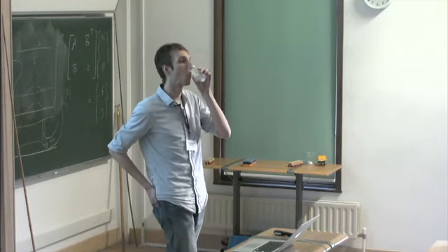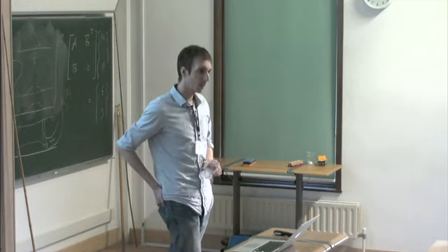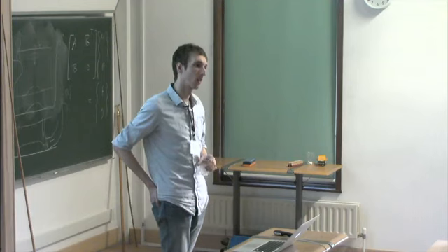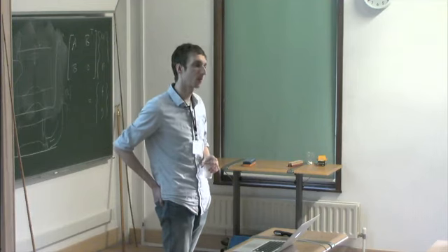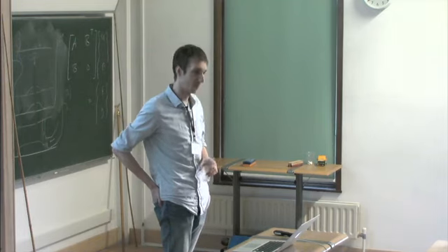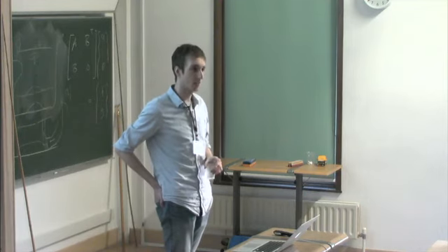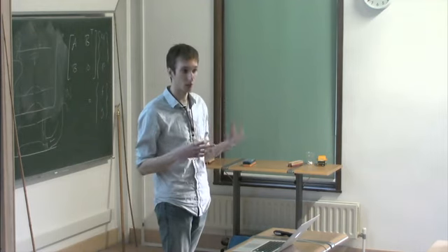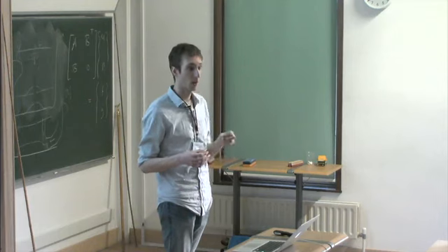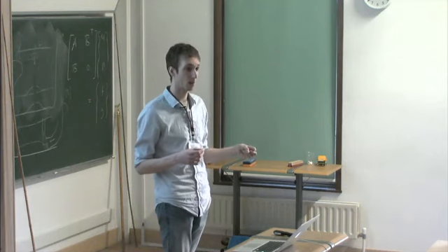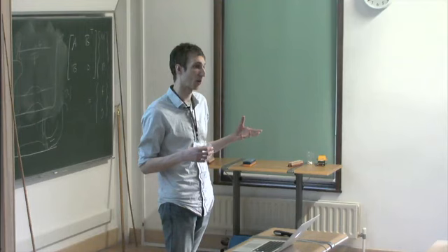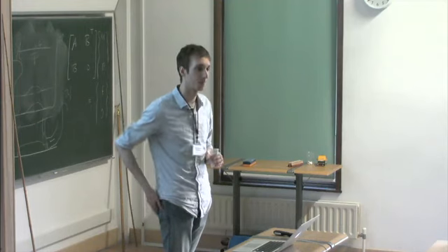As you said, when it is swelling halfway, it's not spherical anymore. Did you do the experiment, or if not, what do you think will happen? You take it out before it has reached final. Would it redistribute, become spherical outside water? So that's a great question, and yeah, that's exactly what happens. So if you swell it halfway, the moisture content is then non-homogeneous, which is what leads to the pattern formation. If you then take it out of water and stop the swelling process, then over time the moisture content will redistribute, and you'll end up with a sphere that's partially swollen. Yeah, exactly.